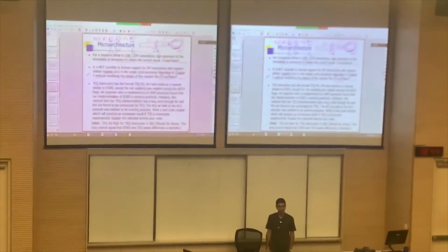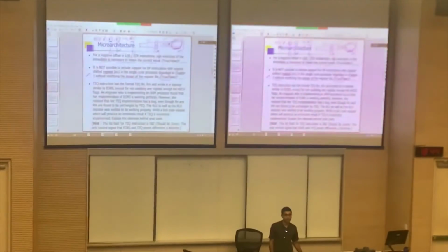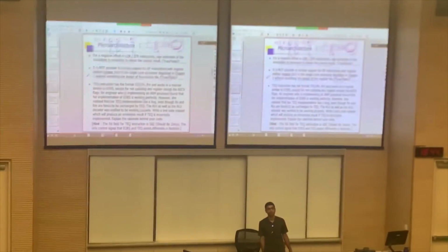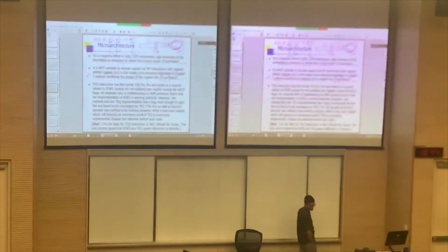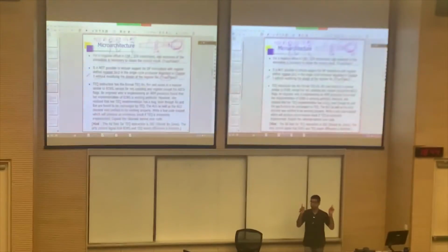How do you do that? It can't be single cycle unless you change the register file design. But if you want to retain the register file design, don't want to change it, you have to compromise on the number of cycles. But assuming that you are allowed to compromise on the number of cycles, what will you do? You don't want to touch the register file, but you want your processor to be able to do this.